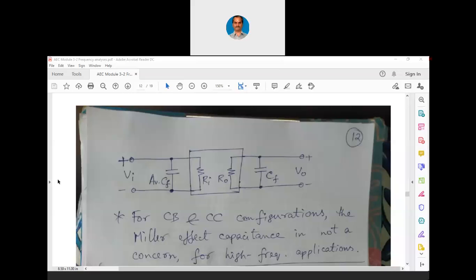Now in case of JFET, when gate is grounded, between drain and source, there is a direct channel, right? There is no junction at all between drain and source. There is a direct connection because it is a single semiconductor. Unlike BJT, where you have collector to base and base to emitter. But in JFET, it is direct connection between drain and source. So there is no capacitance there at all. There is only the channel's resistance. That is in case of common gate.